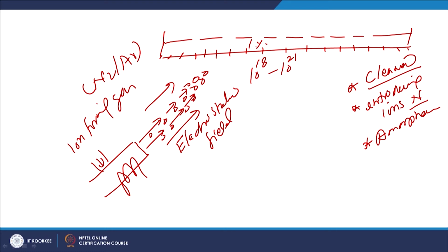The number of ions forming about 1% up to the depth where the property improvement is required, this is like 10 to the power 18 to 10 to the power 20 ions per meter square is required, and approximately 1% of ions will be needed to have these favorable changes at the surface layers.